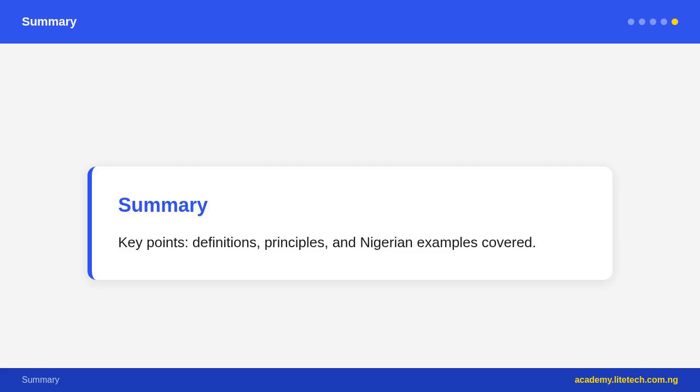AC is used for power transmission because transformers, which require AC, can step up voltage to reduce transmission losses, I squared R power loss. WAEC commonly tests: calculating V0 from VRMS, calculating IRMS and P for an appliance, writing the expression for instantaneous voltage, explaining why AC is used for power transmission.